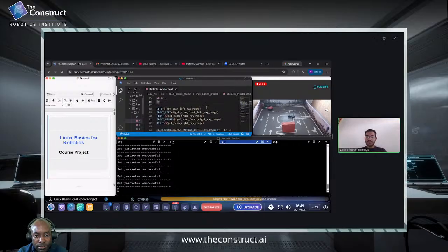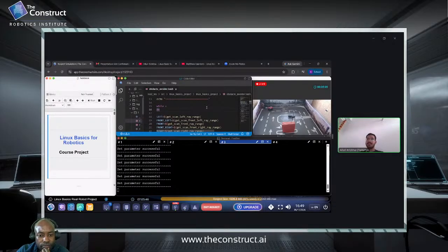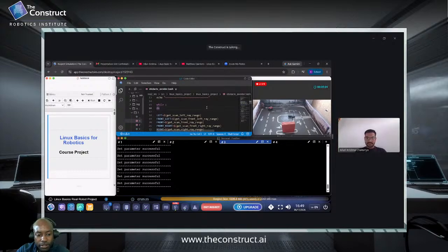I think 0.7 was a bit too large, like 70 centimeters, as you said. What happens is 0.3 is a lesser distance from the obstacle, and the rover can immediately change. But 0.7 makes the rover feel that it can go further, and it's colliding with the walls over here. Yeah, okay, good.